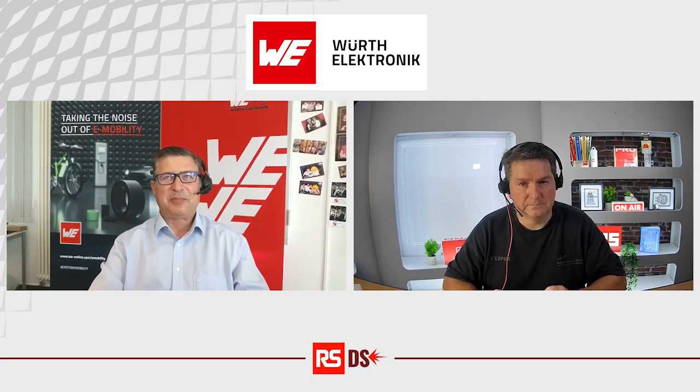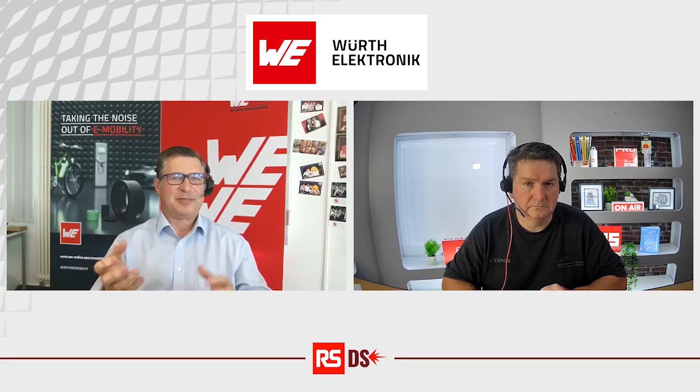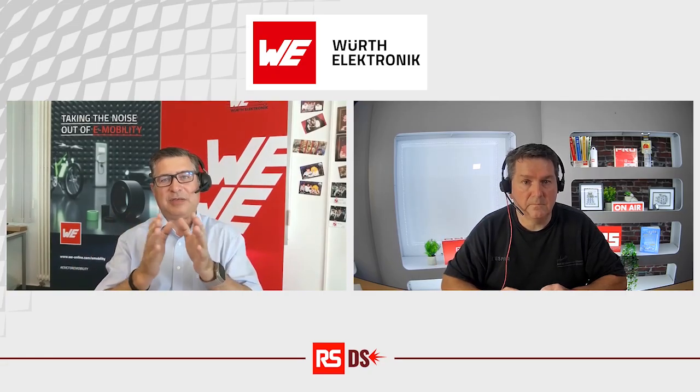Today, downsizing is happening quite nicely, because if you compare the charger from your mobile phone, that old heavy one from a brand which is a Finnish company, you remember it was heavy, and now if you take something new, doesn't matter, a US or Korean company, it's light and it's much more powerful. It is because of the influence of GaN and SiC transistors that the device gets smaller.